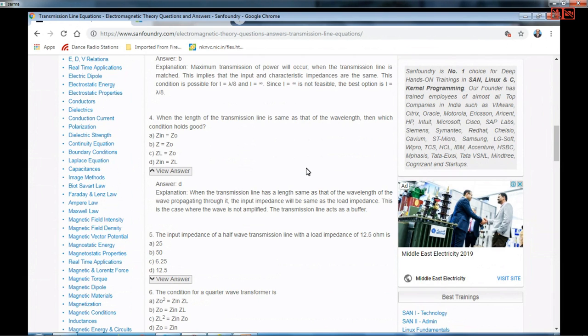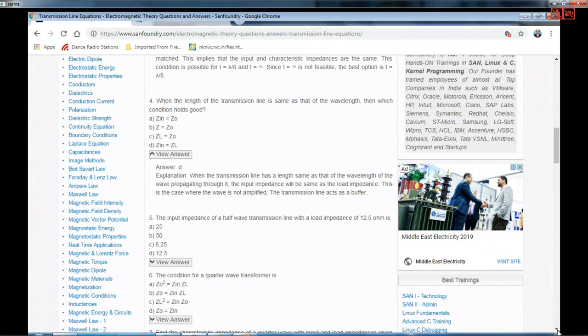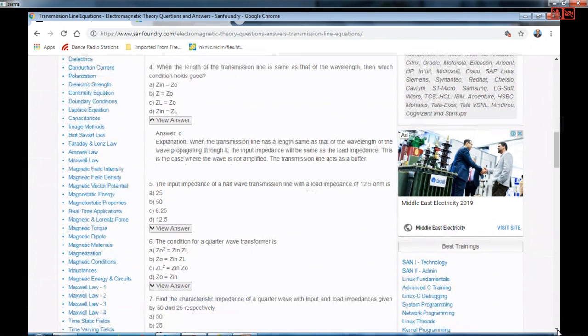The previous signal which we have received has to be kept in a D flip-flop type of transmission line structure so that it can be compared with the present input. So this is a very standard example for that. And if the line length comes out to be very, very large for operating frequencies of hundreds of megahertz or tens of megahertz, etc., then we use alternative methods to realize the operation of the transmission line. Acoustic lines are used. Okay. So these are some additional points which you can keep in mind in this context.